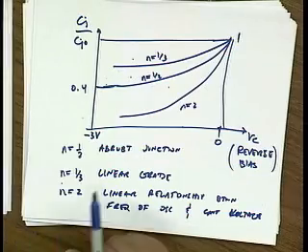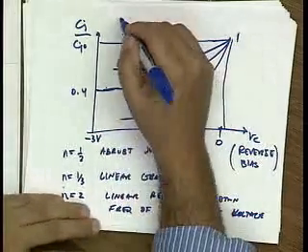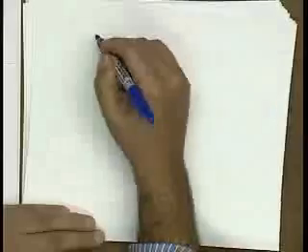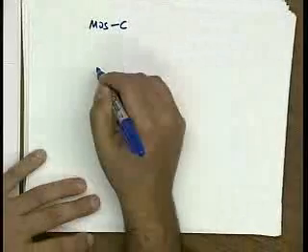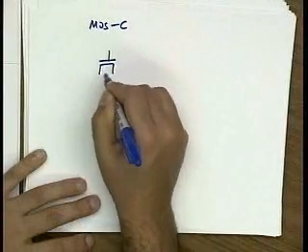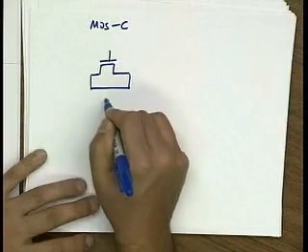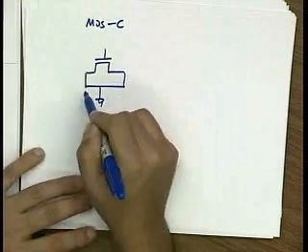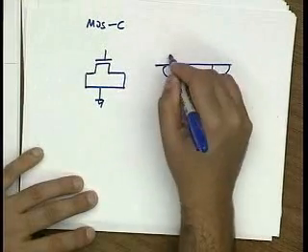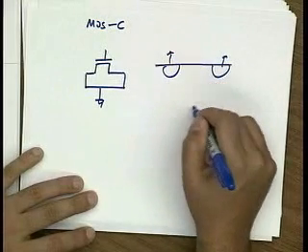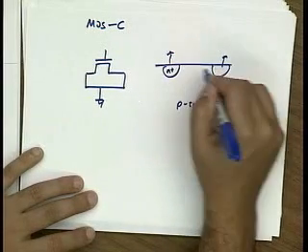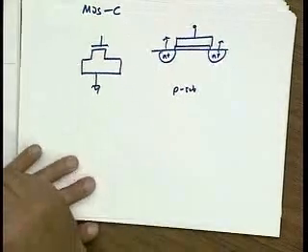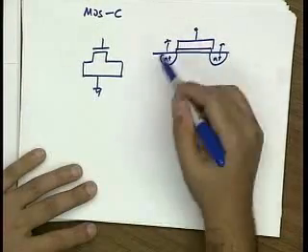So one way to avoid this is, instead of using a PN junction diode, so this is a diode characteristics, is to use a MOS diode. So MOS capacitor structure, as you guys all know from 105 and 130, looks something like this. Basically, I'm going to tie my source and drain together, and let's say I ground it, and let's say that this is P sub, and so this is N plus, this is N plus, and then I have my gate here. I know that the capacitance of this structure varies depending on what region I operate this device.